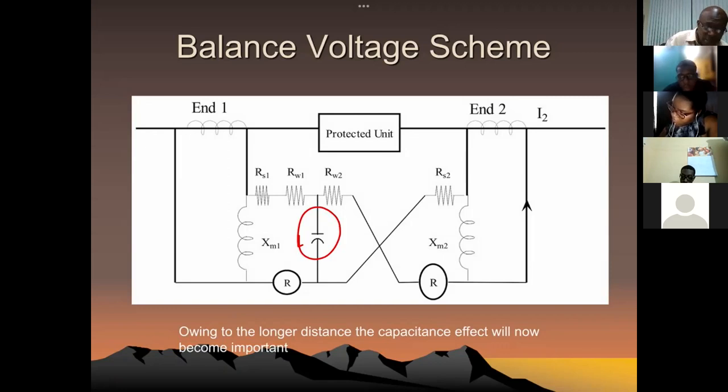What this means is that the capacitance is inherent to the pilot wire, even though we twist those pairs to deal with the capacitance, so we don't allow the pairs to lie parallel for the entire distance.